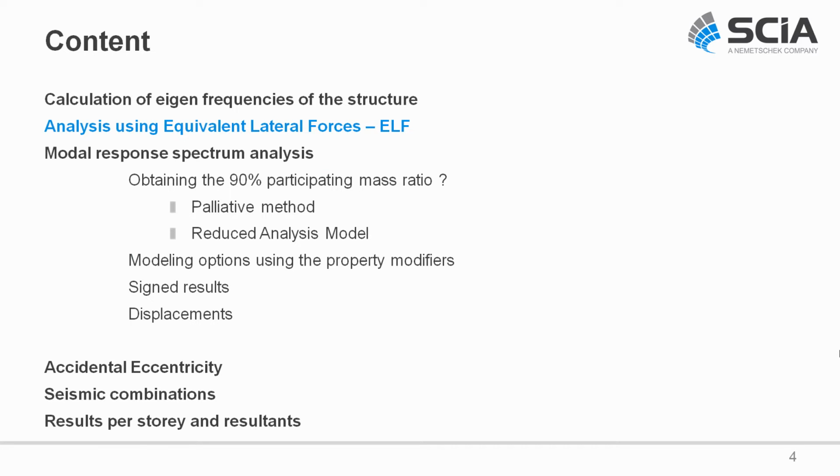Okay, now that we have calculated the vibration frequencies of the structure, we can start by defining the seismic action. We will start with the method of equivalent lateral forces, or ELF, that was implemented in SCIA Engineer from version 15.2.